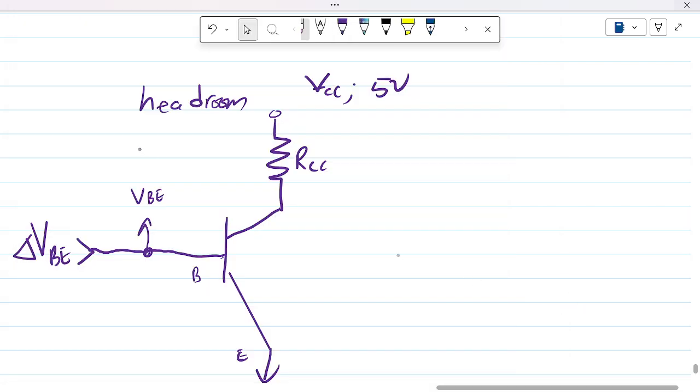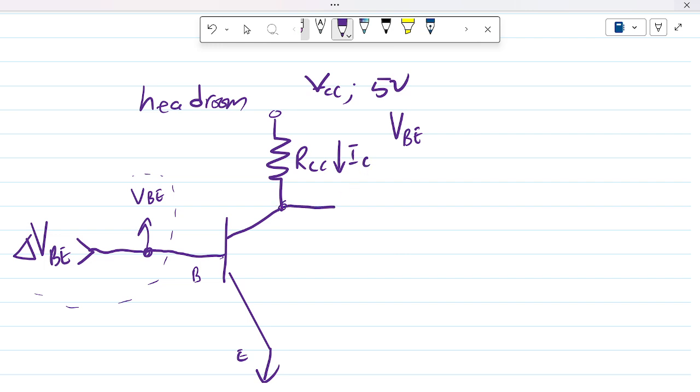In this video, we are explaining headroom. Now, before any signal comes in here, let's say VBE, the bias, there's no bias voltage. That means there's no collector current, IC. So what will be the V out? Since there's no collector current, V out is VCC minus 0 collector current times RC. So the output voltage is the same as VCC, which we are taking to be 5 volts.